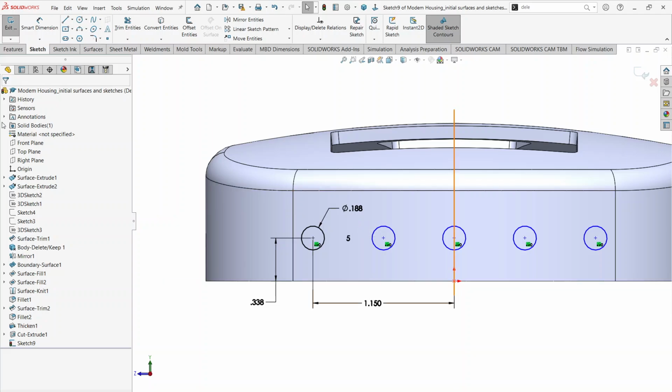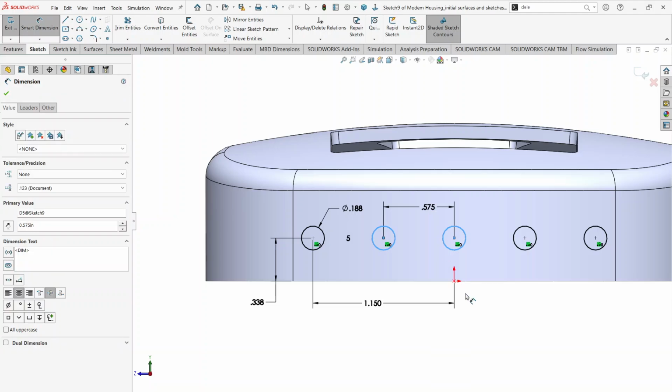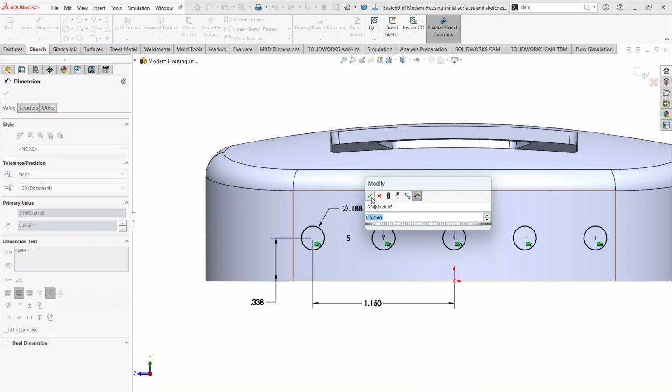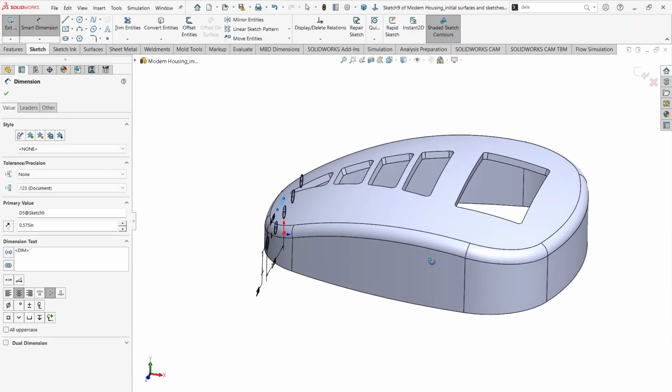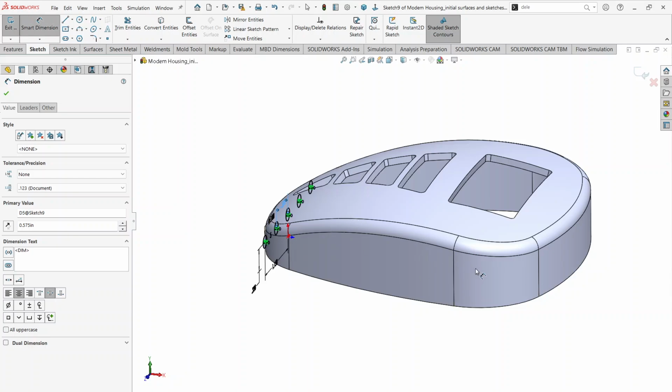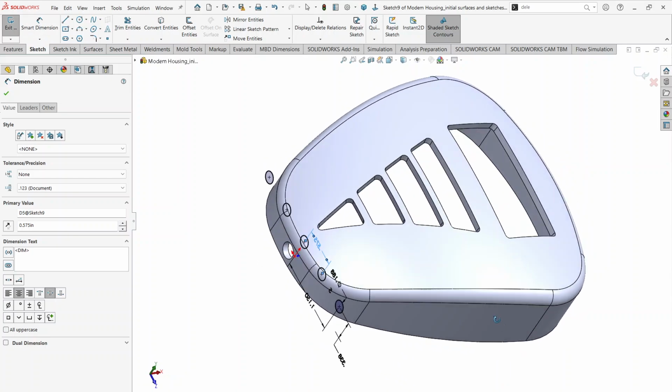Okay, now you can create your hole. If you wanted to make sure that this is fully defined, you can dimension one of these 2 sketches to make sure that it is fully defined. And then having that, it should be from different direction, right?